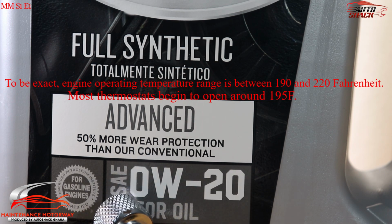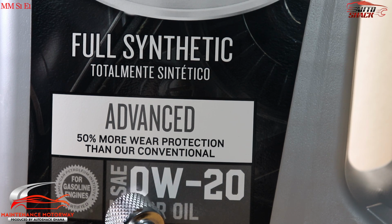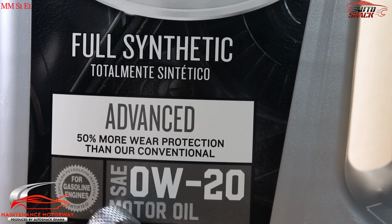What this means is that the oil should be able to operate at a zero thickness, which means it needs to be really thin during cold weather or winter, actually about minus 18 Celsius, which is about minus 1 Fahrenheit. During the cold weather, it needs to be thin enough that it can flow quickly to protect the engine when you start it.